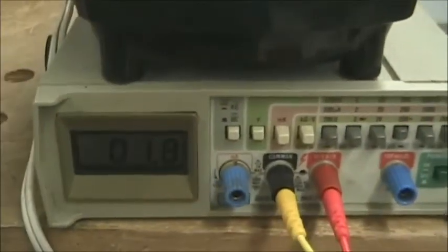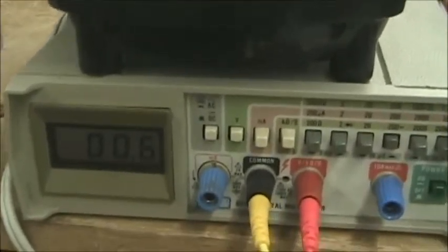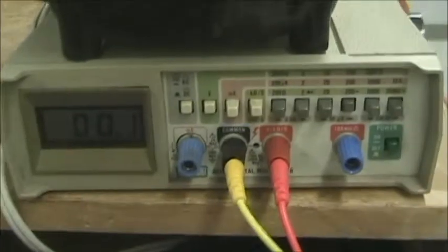I can go up a little higher. You can hear it speeding up a little bit. This unit also has a high speed. So when I switch to high, the voltage jumps up, and then the max speed is for full voltage. So that's how series motors are used in appliances for variable speed. Of course, speed is primarily dependent on the load, because that's what determines the torque that's being developed.